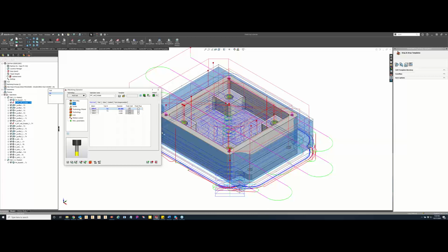Yeah, absolutely. And one thing I don't think I mentioned in the last iMachining night classes is that the feeds and speeds will be based off of how much of that tool is sticking outside of the holder. Let's say we're having a small little cut here, but I have 6 inches hanging out of the tool holder. iMachining is going to factor in that 6 inches versus 2 inches sticking out of the holder. We're going to get some flex, and iMachining with the built-in algorithm will automatically calculate for that stick out too. So it really is hitting the easy button, taking out the guesswork for you guys.